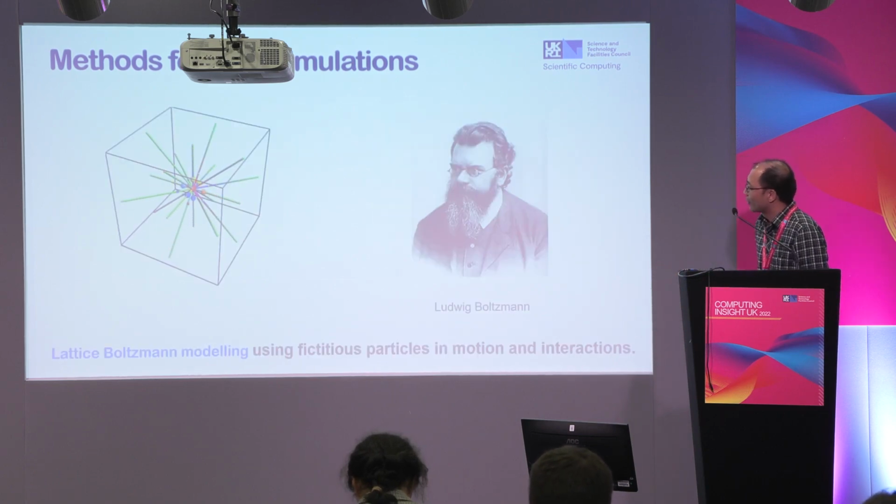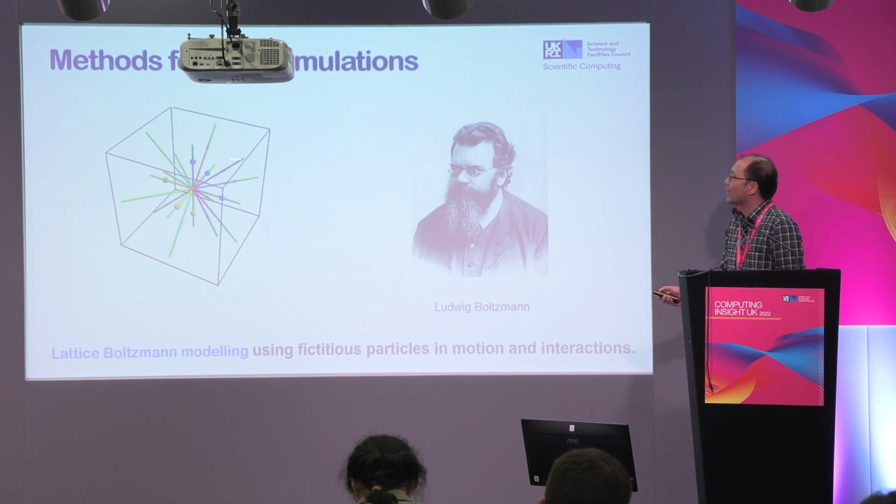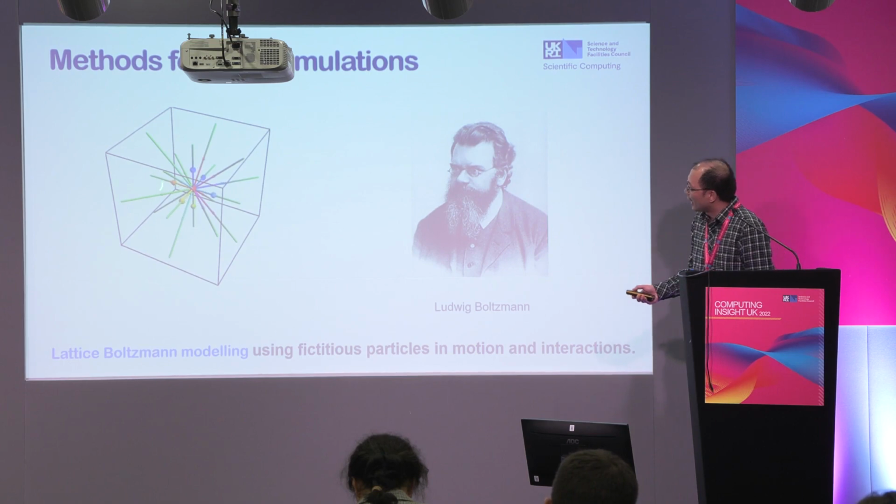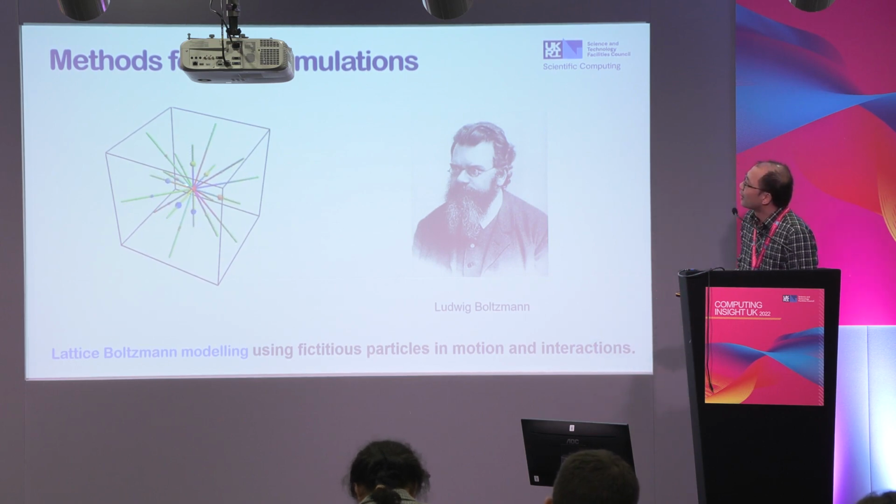Another method is the so-called lattice Boltzmann method. This is a relatively simple and standard method. Basically, the whole algorithm can be summarized by this animation. We have a number of particles. These particles move in certain directions, then they collide or interact with each other. After collision, they go away again. The collision rule is specially designed so that we can correctly recover or model the fluid flow.